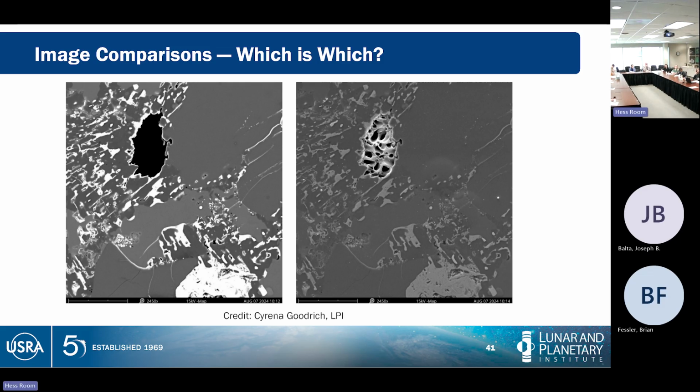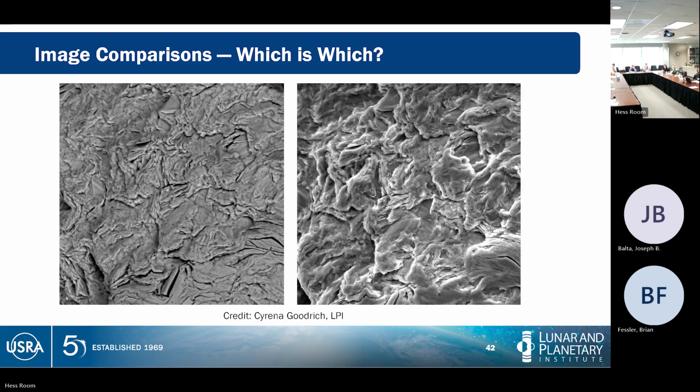When you look in secondary electrons on the right, you see it has holes in it. So you can ignore it. It also shows that in the backscattered image, you see phase contrast between, say, this area and this area, which are in fact different minerals. Whereas in secondary electrons, you can barely see that, because you're not getting the composition.